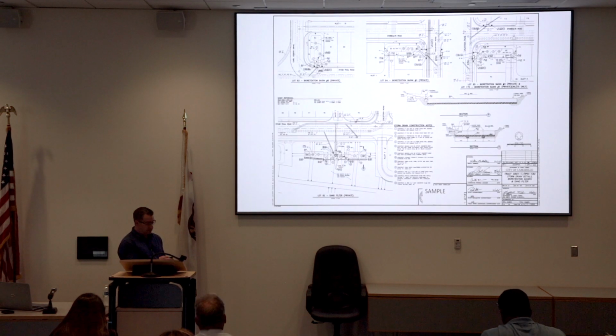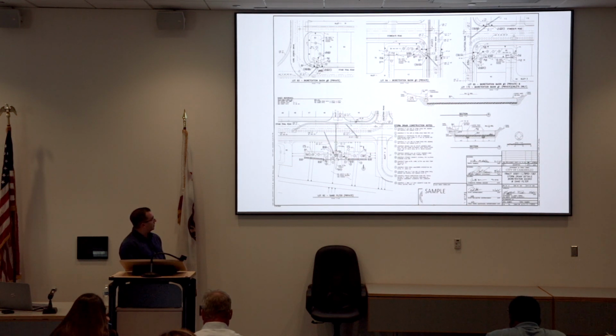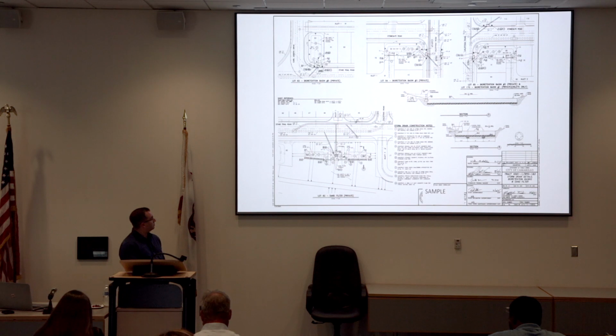So this is actually the plan that shows that sand filter system down here. And if you notice, you see this berm slopes down and down, but you have another basin over on this side too. The sand filter system comes down through this pipe, and then it gets choked off into here, and then it fills up these basins, and then if need be, it can find its way back into the system. But any high flows are going to bypass, and they'll go down through this line.